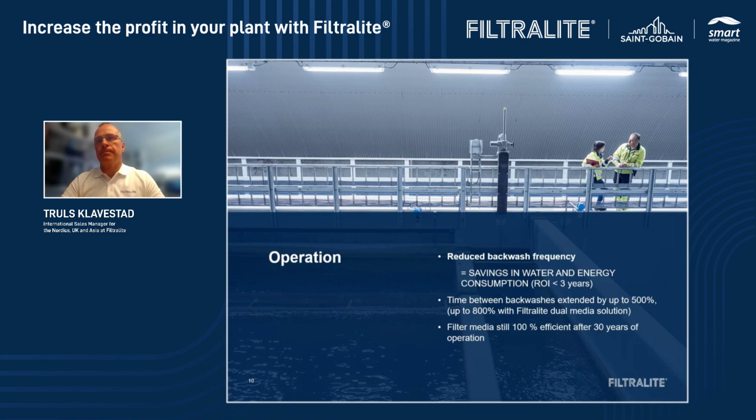We have seen that the client have payback time down to 1 year and sometimes as low as 6 months, because they have some problem and they are using sand, and very often you see in the sand filter clogging in the upper part, and they need to backwash maybe 2, 3, 4 times a day. And for sure, all the time when you do the backwash, you lose production. Water you could potentially sell.